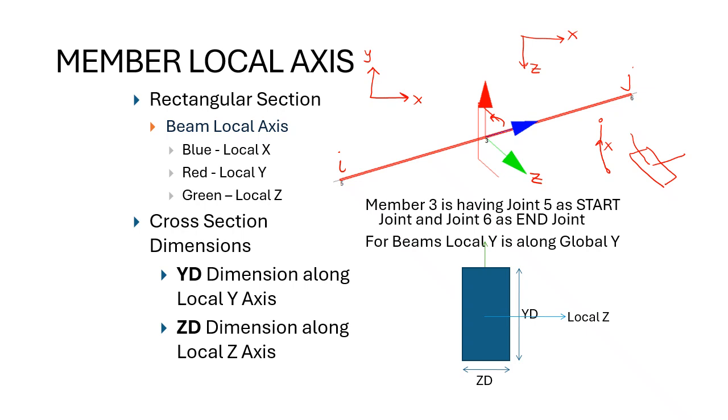If you want to define steel, it has a library of all international shapes: European, American, Australian, Korean, Indian, and Chinese cross sections are all available. Again, we can pick a different profile like I, H. In British, it is called UC and UB. And in the case of European, it is called IPE and HE profiles, H profiles. So we have a complete library, and you can make built up sections also.